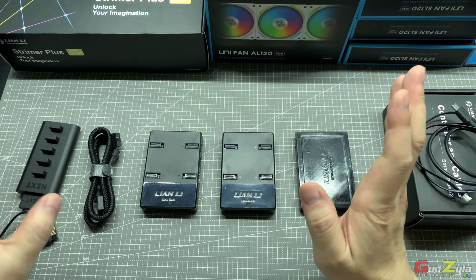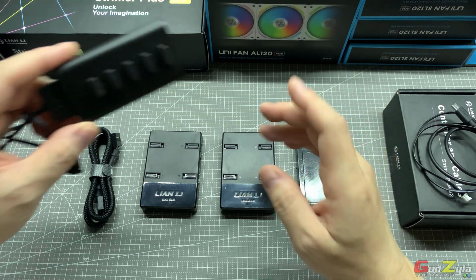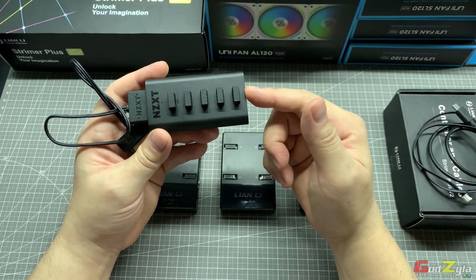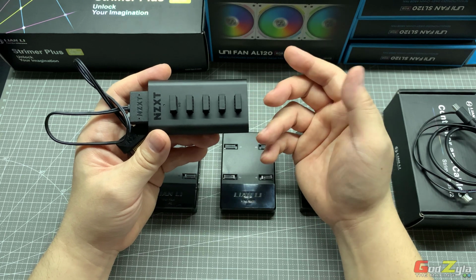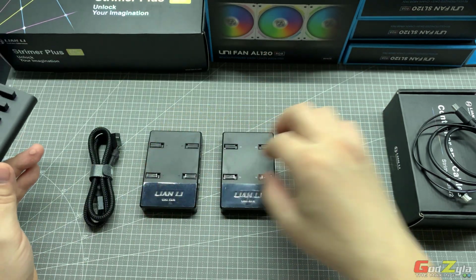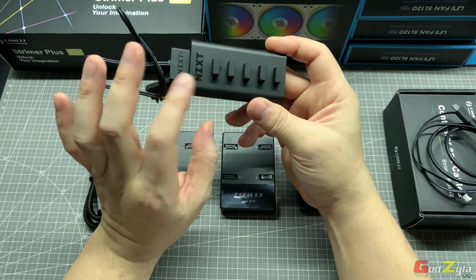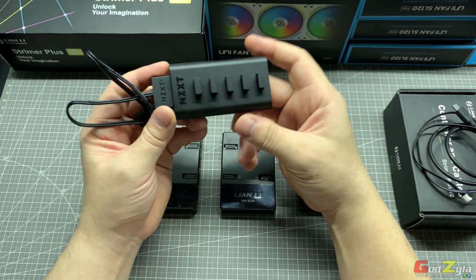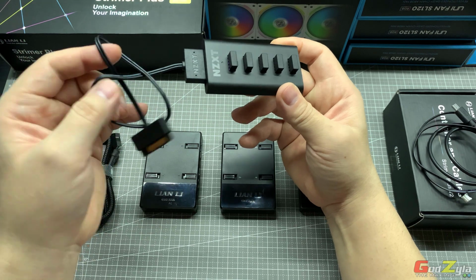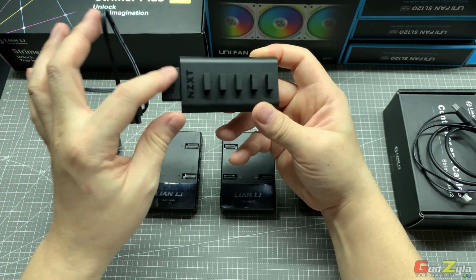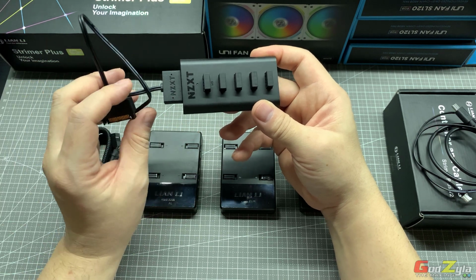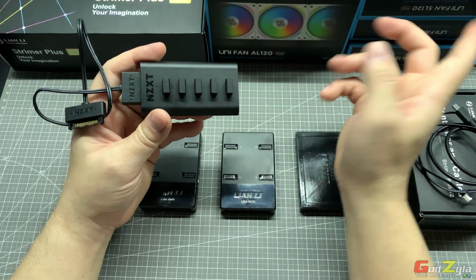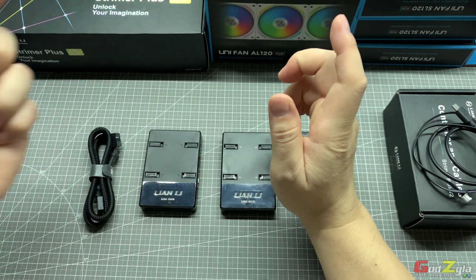Now, speaking of which, earlier on I did mention that to get a hub splitter for USB itself. Now, the reason to have this, most motherboards come with either one or two USB headers. So if you have more controllers like I do, you might need to purchase a separate unit. This is actually the USB splitter, or should I say the USB hub. Make sure you get a hub that comes with a SATA source that draws power straight from your PSU. If you were to just get the splitter, that might not work, as there's not enough voltage to provide when you connect to the controllers and to your motherboard header. So make sure you use this.